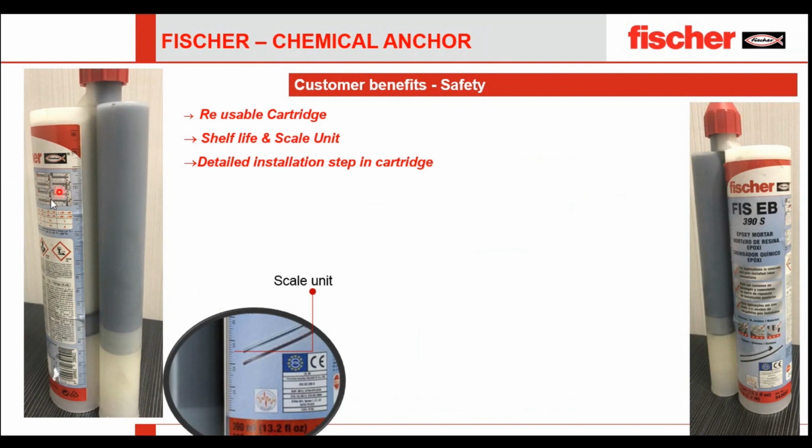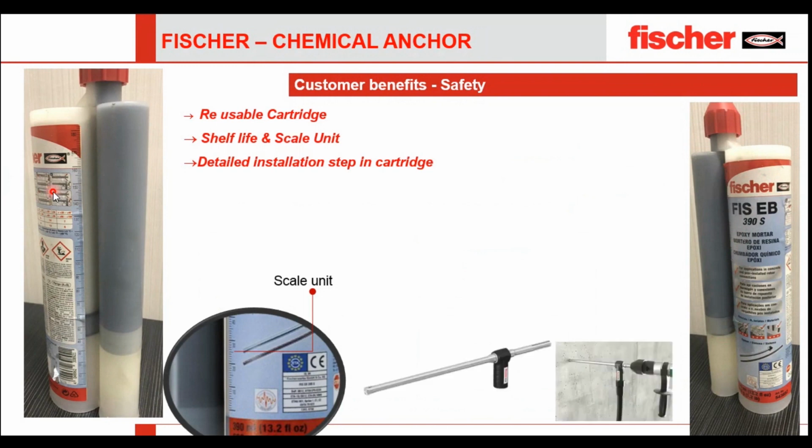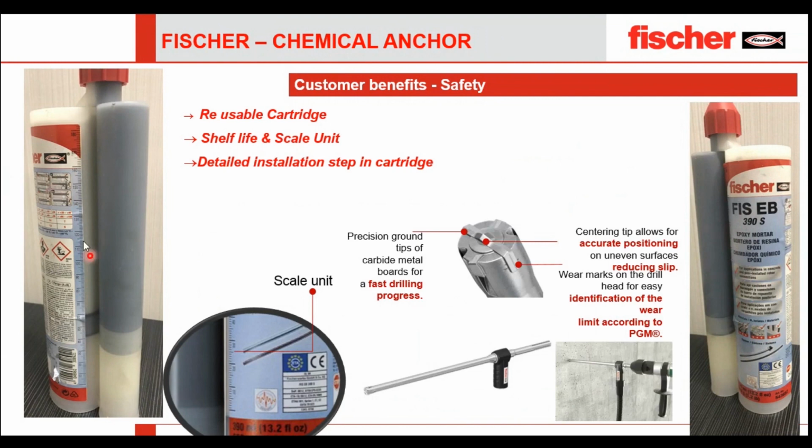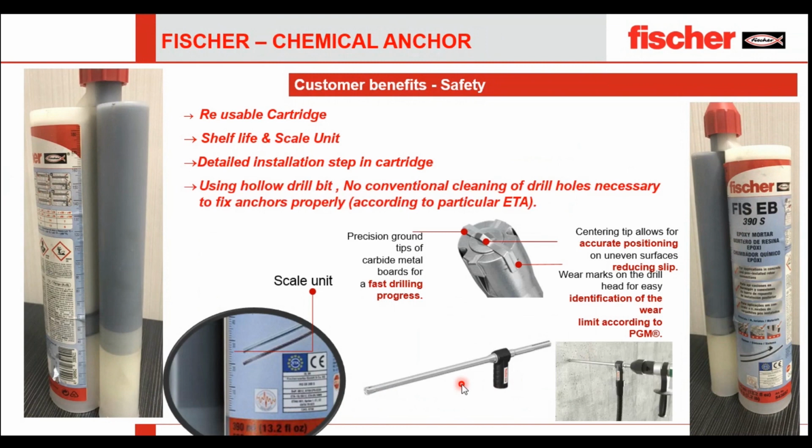Again, the detailed installation steps will be here. How to install, at what depth, and what are the proper drill things we can install. And also we do have a hollow drill bit coming along with the cartridge. The best part of the hollow drill bit is that using it, there's no conventional cleaning of drilling holes necessary to fix hangers properly, which is according to the particular ETA approved.